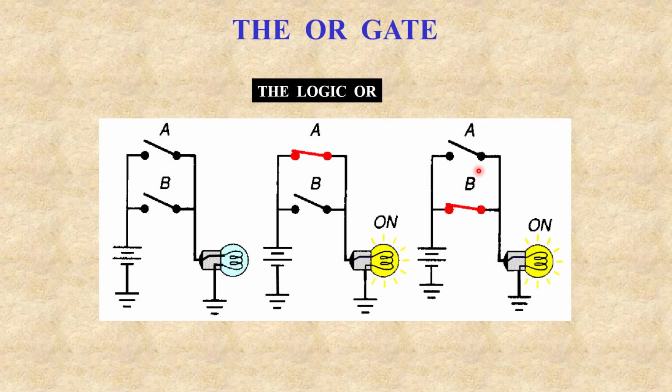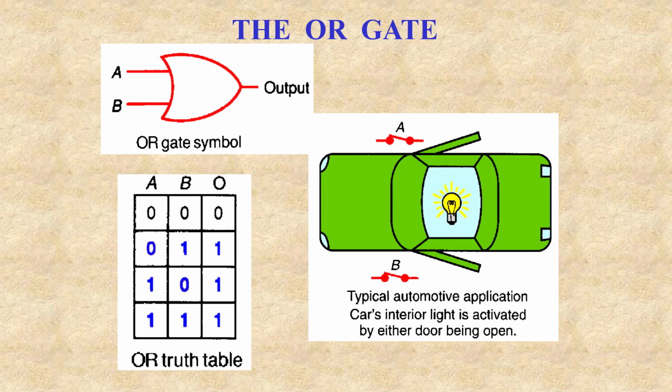Now here's an OR gate. We talked about these as well. In an OR gate, because these are wired in parallel, if A or B is high or true, then we get a true on our output. There's the schematic symbol, and there's no relays or contacts inside of this. It's all solid state transistors, but the circuitry is such that the logic is performed that if A or B has current or voltage on it, voltage appears at the output.